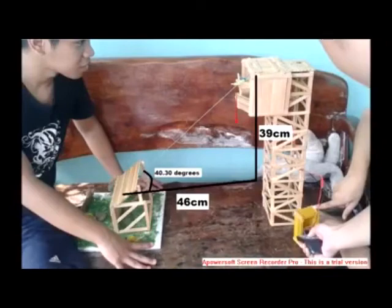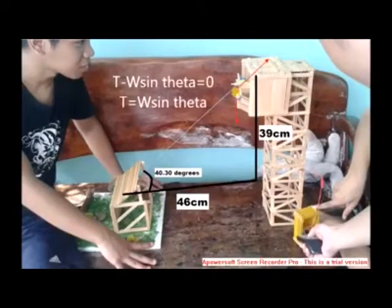Then the next thing we will do is to get the tension. This is the tension. From this free body diagram, we get the equation T minus W sine theta equals 0. Therefore, the tension is equal to W sine theta.